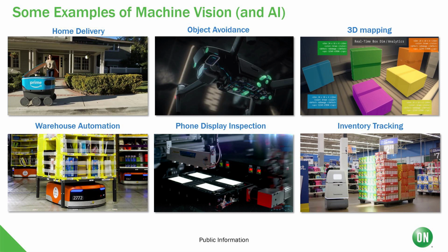In the upper center here, we have an example of a drone or object avoidance. Here we have global shutter image sensors running at a very high frame rate, looking for possible obstructions or devices in the path of the drone. This can be very useful for a drone that's not fully controlled by the user, but directionally controlled by the user. Move forward 10 feet, move forward 100 feet, don't hit the telephone pole. And of course, the advancements in the image sensor and the CPU now allow a device like that on its own to move around a stationary object.